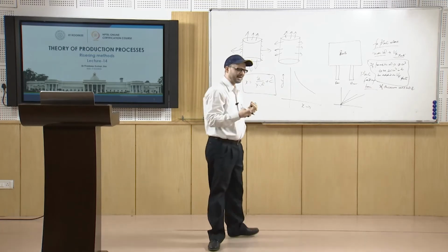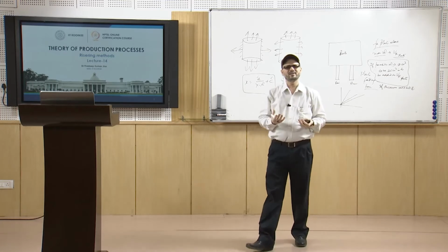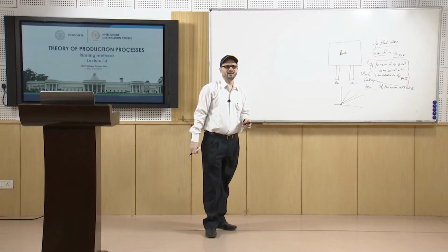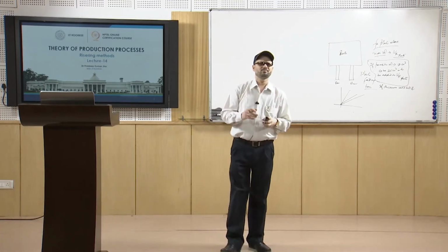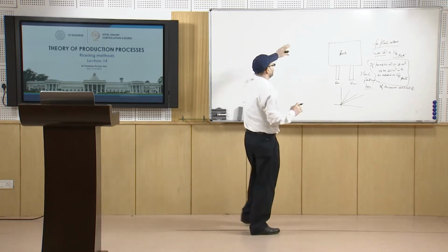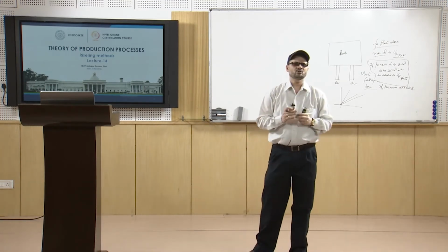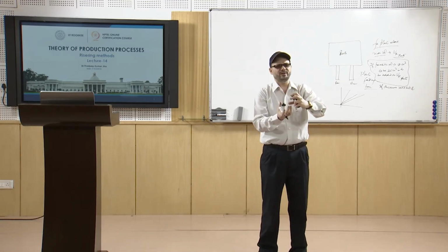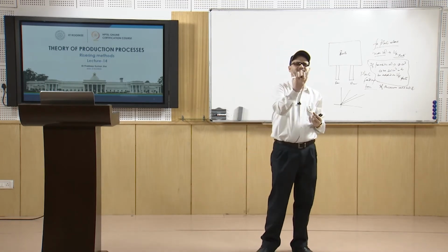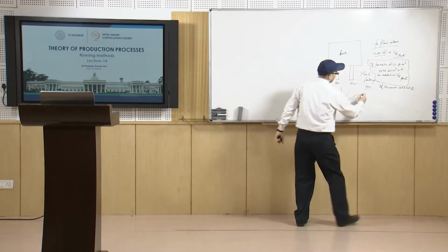So this method has that advantage also, that it is used for calculating the riser volume even in the case of appendages. Next, sometimes for hollow cylindrical shapes, when you have hollow projections, the shape factor is altered. Suppose you have a core in between; depending upon the diameter of the core, the correction factor applies to the shape factor L plus W by T.